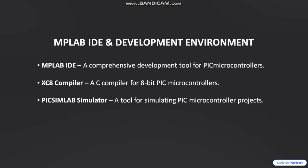MPLAB IDE and development environment. The MPLAB IDE is a software tool used for writing, compiling, and debugging programs for PIC microcontrollers. The XC8 compiler converts our C code into machine code. PICSimLab is used for simulation, where we can test our project without hardware. These tools make development easier and help in finding errors before real implementation.